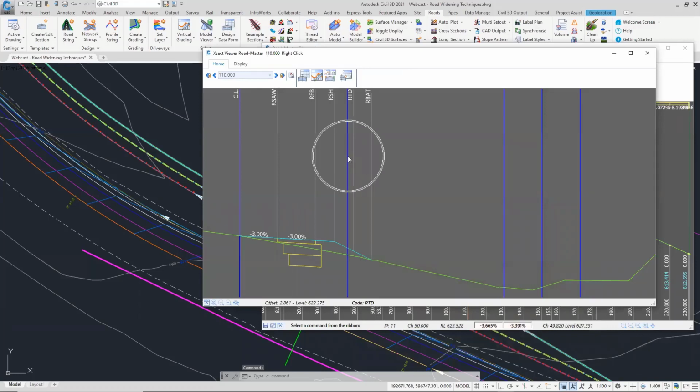We can have those visually shown in the cross-section window, and it's an extremely good discipline to get into because it helps you see and contextualize your whole design. So I know that the saw cut has to match onto this alignment, the EB, the shoulder, and the table drain have to marry up to those particular alignments.